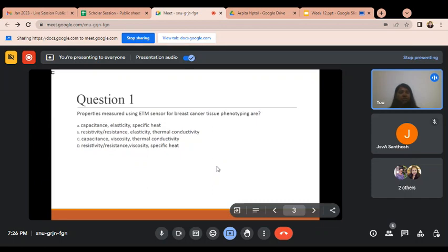When we pass current through the boat, it heats up, and the source material on it starts to evaporate and is uniformly deposited on the substrate placed on top. This is also a PVD technique, physical vapor deposition.